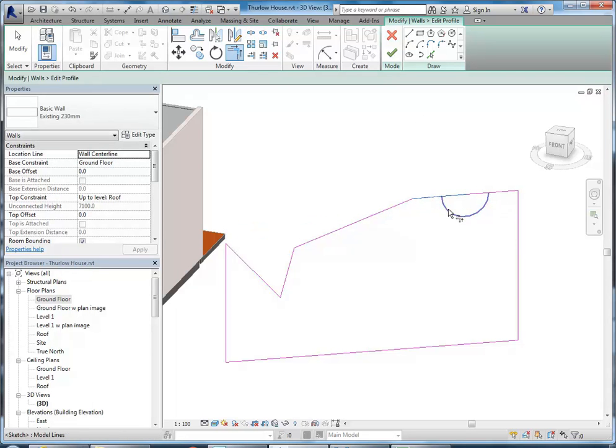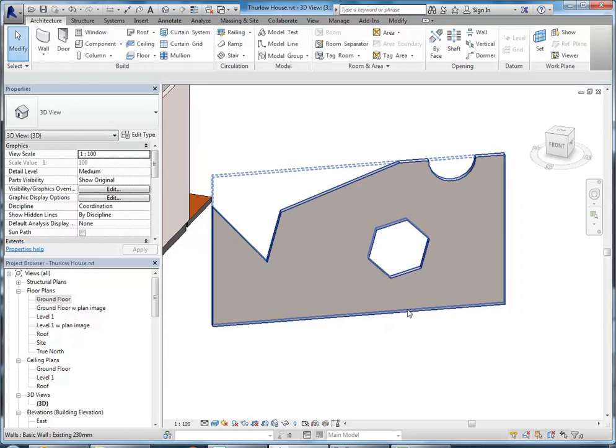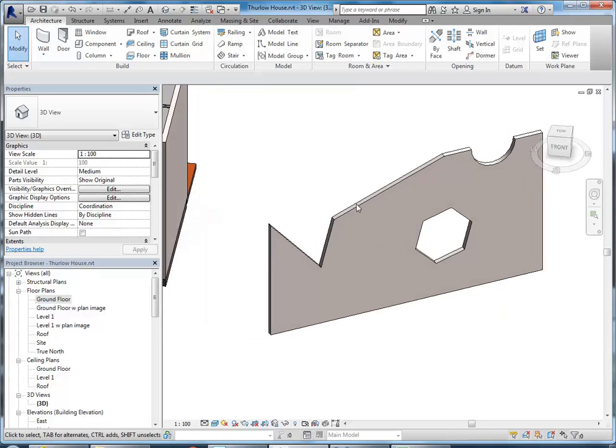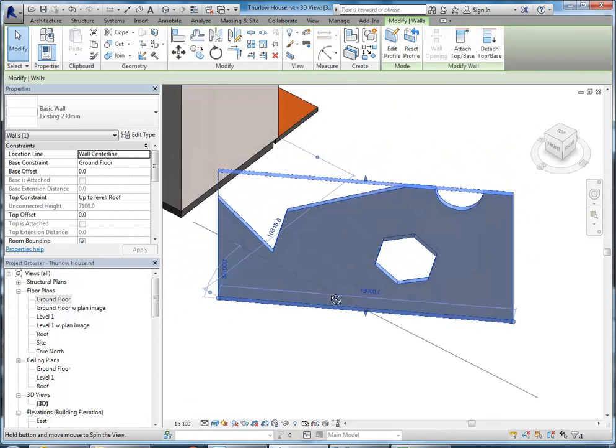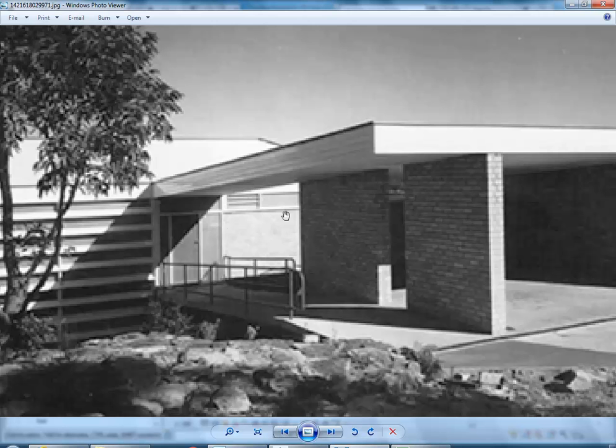Again, essentially what I'm doing is changing the shape of the wall in elevation, and I can put holes into the wall this way as well. So it's a really useful way of putting openings into walls. Okay, so it's an extremely useful option, but here we're just going to use it to give the wall a stepping height. Because again, if it's not clear, we've got this brick wall, which I'm assuming would continue underneath that walkway there and still be brick. Well, that's the way we'll do it initially anyway. And then the curtain walls will just fit in around that.